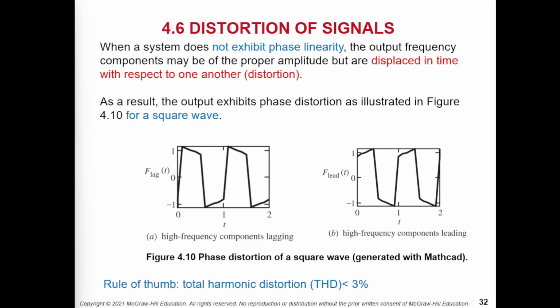Because I have worked on hearing aids for a long time, for hearing aids or some hearing devices, THD of 12% is the limit. That means everybody can distinguish the good one from the bad one whenever THD exceeds 12%. But for 3%, I think only a small number of people can distinguish. We call them golden ear, 金耳朵. So, understand?